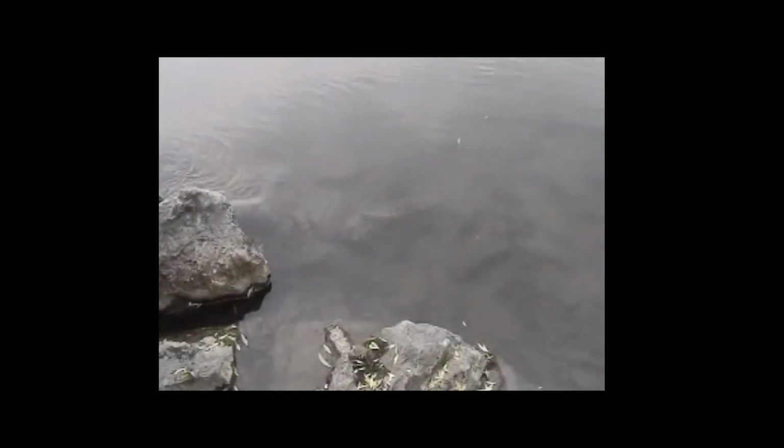In a few cases, it's more useful to follow a specific fluid mass through a flow field using a Lagrangian reference frame attached to the mass. Here, the blob of white water is followed as it moves downstream. But if we mark the instantaneous boundary of the blob of fixed mass at a certain time, then we can watch the water flow through this boundary while the original white blob flows on. This is the Eulerian approach.